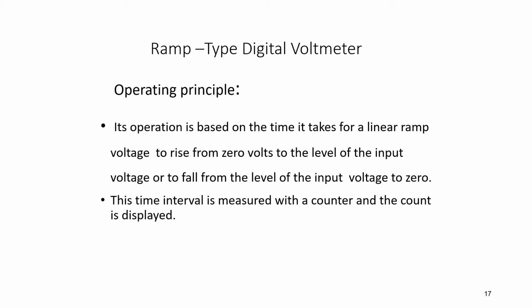We connect this voltmeter in the circuit with a higher range and then select the required range depending upon the way the reading is observed. Supposing it is showing 0.005. If you want to read it comfortably, reduce the range so that it will show you the correct voltage reading. So in this way, we can use the digital instrument.